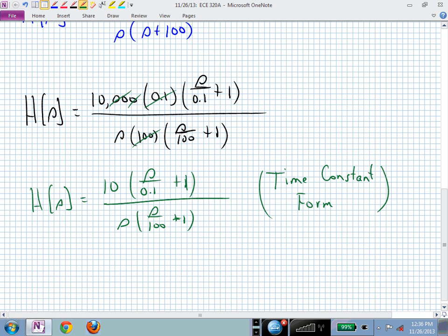Not very long you would have to wait. You don't have to worry about the zeros when you're dealing with time constants in terms of transients. Some of you on the test were looking at the zero's location and using that to determine your slowest time constant, or your longest time constant.